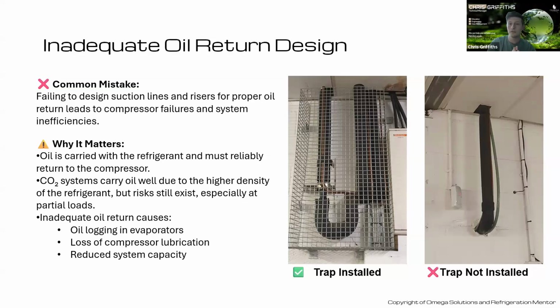So we still have our rules of thumb for design velocities, as we touched on slightly yesterday, but making sure that's actually implemented on site is very important. I've known of sites where the designers have designed it correctly, and they've shown risers maybe 1 or 2 pipe sizes down, as you typically would, and the installation engineers on site just say, well, we've not got that pipe, let's just use that pipe instead. But we haven't got to get reducers as well. Well, you're risking a lot there.